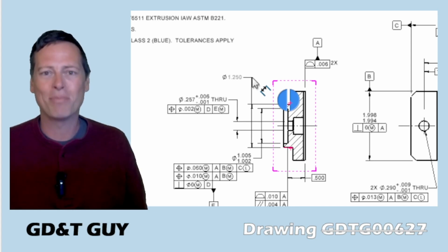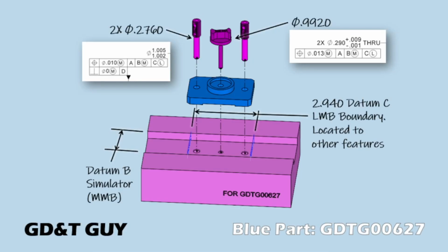Hold some of these thoughts for episode 4. So here's what I've had to wrap my head around. This whole thing has been about functional datum features, right? And I have kind of equated that with the locating features, which is usually right. Well, this datum C feature, this 3-inch width feature, just fulfills another functional requirement, right? It's not to locate the part. No, it's to ensure that there's enough material outside of these screw holes. Its function is to be there.